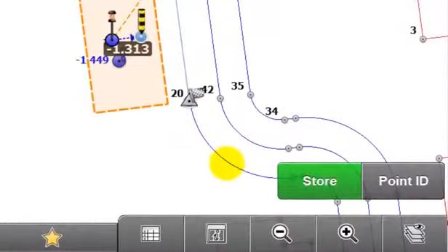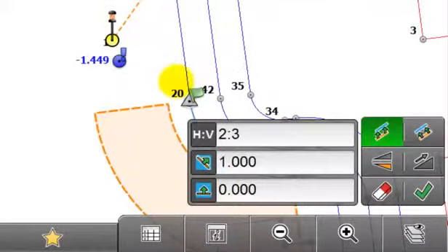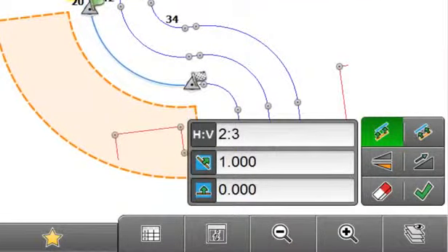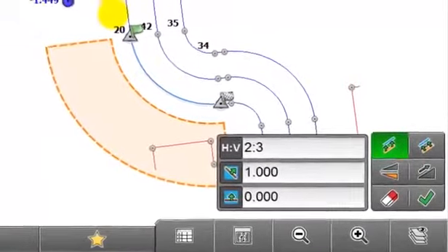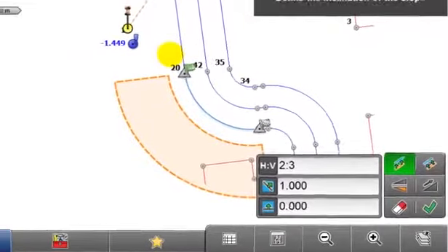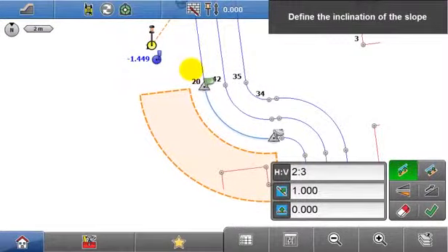Tap another data set and a profile is immediately created, ready to be checked in the same manner, with the same grade and offset applied. So the Slopes application is a convenient, fast and effective way to accurately monitor the construction of profiles in the field without the need to spend any undue time in the office creating data. The data you need can be created very quickly while still in the field.